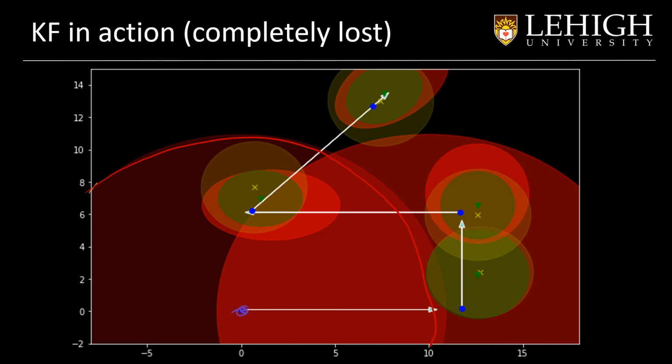If we run the simulation, the estimation gets smaller and smaller every time we run the Kalman filter and combine the information from the odometry and the measurements. In the end, this estimation is significantly smaller than the initial one that we had.